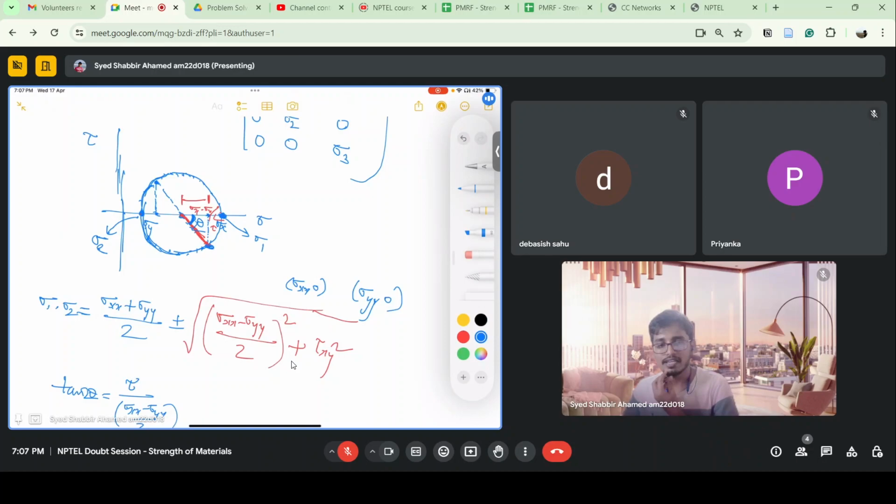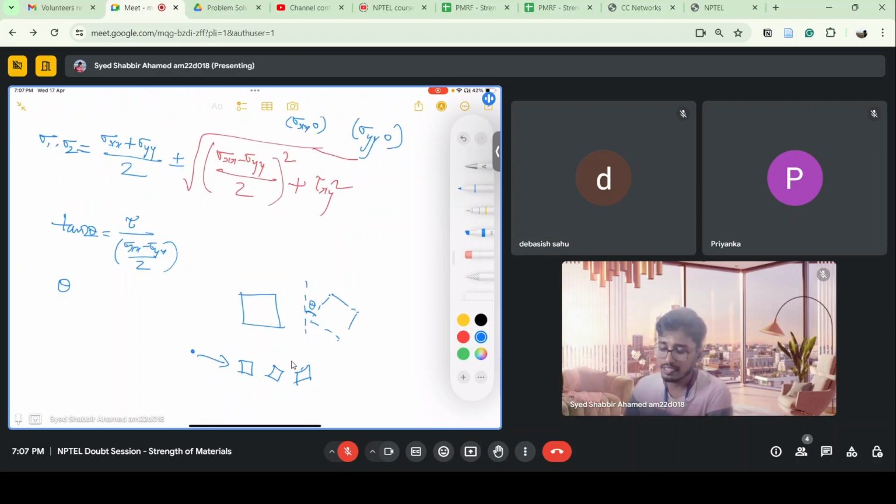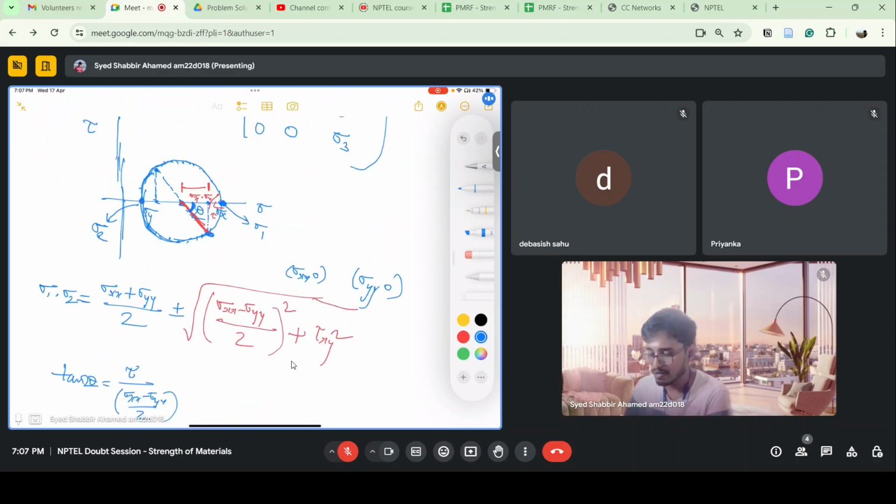So Mohr circle will give you on what plane, what is the stress. Simply using the circle, you can say on this plane this is the stress which is occurring, without much calculations. You can use stress transformation using the stress tensor and all, but that is a more complicated thing. If I know the Mohr circle, I know the orientation. If I want to know at theta degrees from the initial x plane what is the normal stress and shear stress, I can just use the Mohr circle and I can get that. So things become very easy.